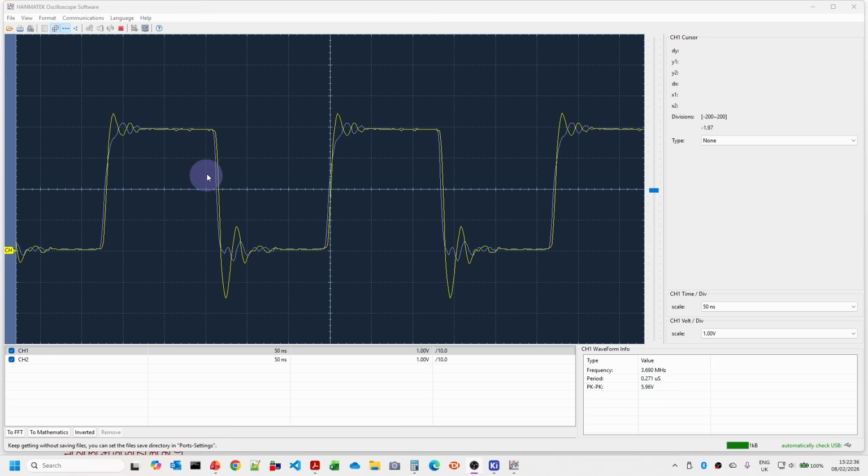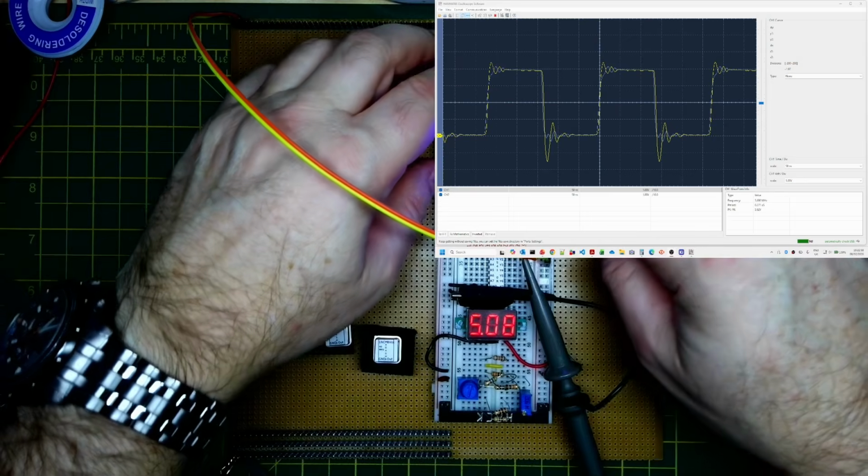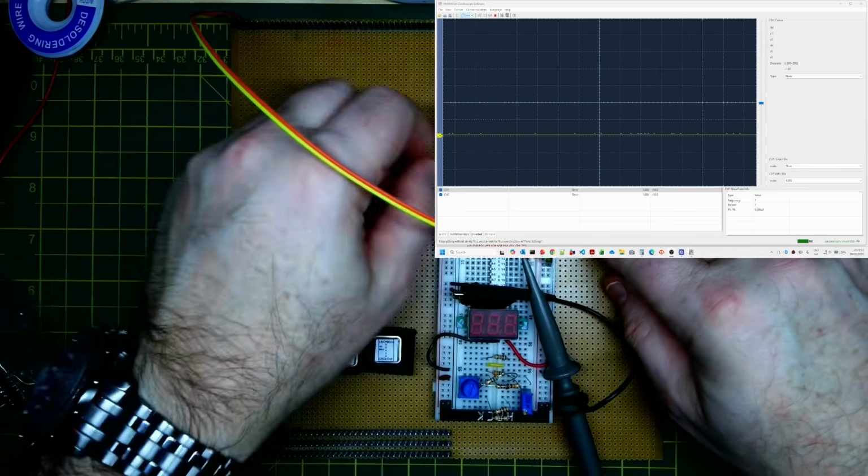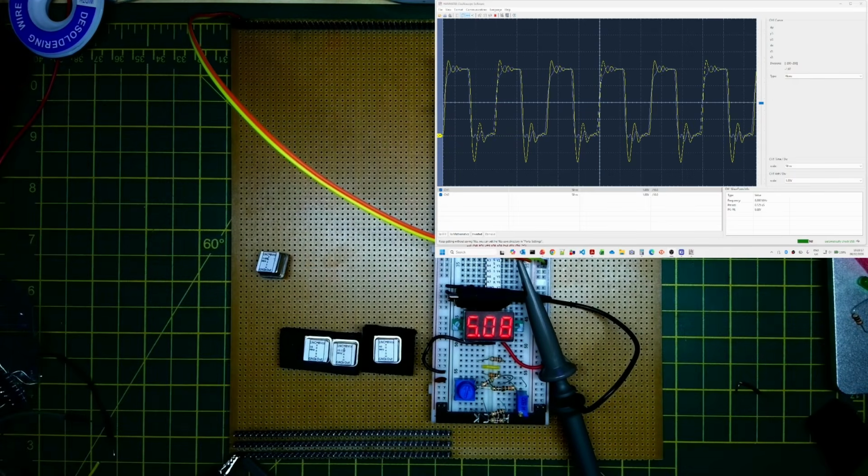Now this might be something that we would have to worry about, because a lot of the chips will allow a certain amount of undershoot, -1 volt for example, but I'm not sure whether -1.5 volts is going to do any good. So let's switch back to the other view. Now I'm going to swap out the 4 MHz one and try the 8 MHz by switching that on. That's similar, obviously a higher frequency. There's still an undershoot of probably about 1.5 volts there. But the actual signal, apart from the oscillation on the rising edge, looks reasonable.